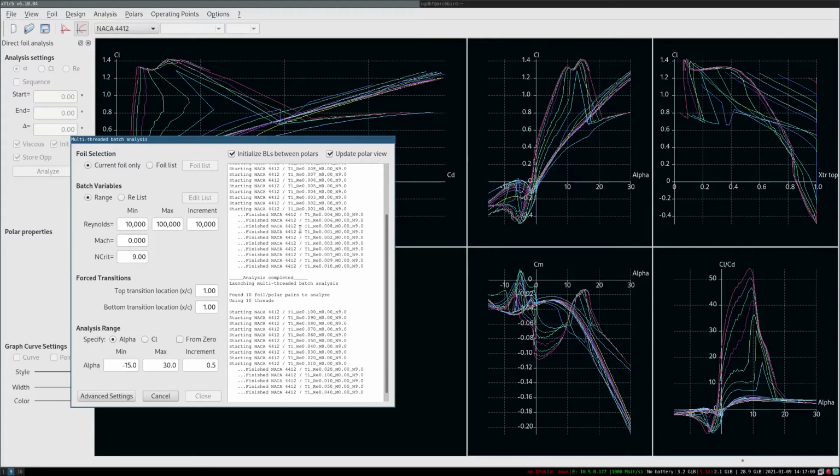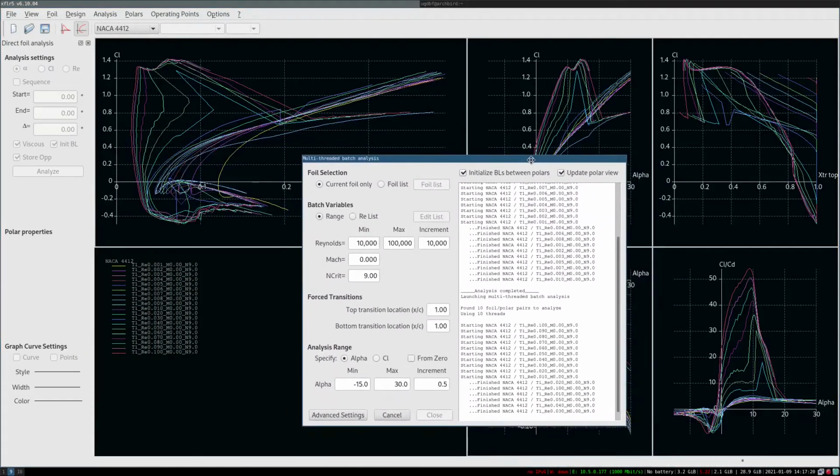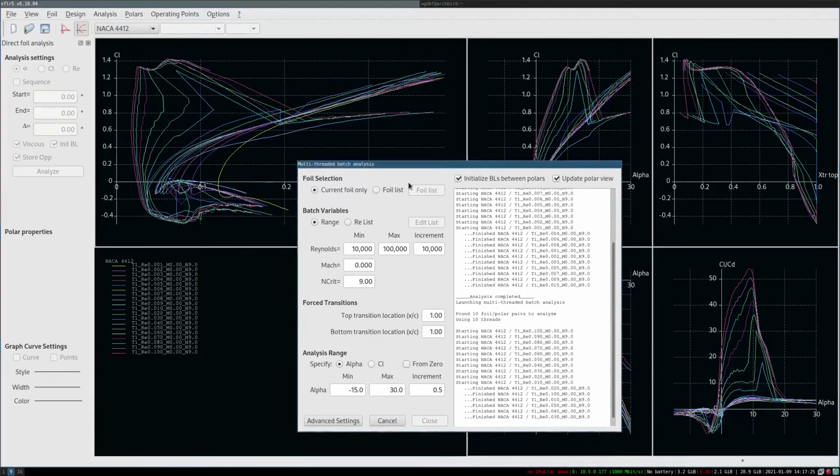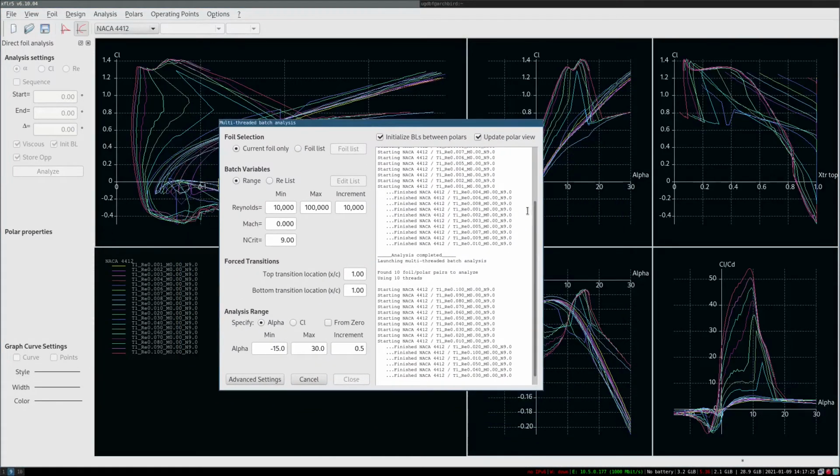It just works the way that, if you read into how XFoil and the 2D methods within it work, some shapes just lead to incorrect behavior. In this case, everything is progressing relatively linearly or smoothly, and we don't have large discontinuities all over the place, so this is borderline acceptable. These jaggies are not great, but again, they're not the worst I've seen.